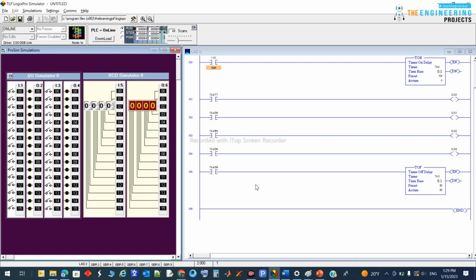So how do we make a retentive timer? Or the question is, do we already have a retentive timer, or can we make this retentive timer? Let me see together with you by moving to the toolbar for the programming. Here in the timer tab, you can see this is TON, we talked about the TON, this is TOF, we talked about the TOF, and also we have the RTO. These are the three main timers that you can use to make any timing related logic in your program. So let's try this one and see how it is working.